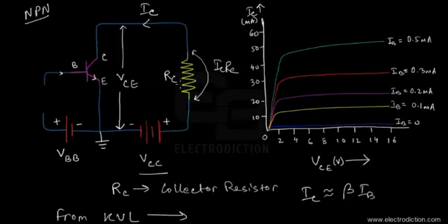And once again, if we connect the open circuited input loop once again and let flow the maximum amount of base current that the BJT could tolerate, so I'm just writing it down as IB equals IB max. Under this sort of situation, the BJT would be driven into the saturation region, and the collector current would be maximum as well. So we'll have a collector current of IC equals IC max, or rather we can just write it down as IC sat, which means IC saturation.